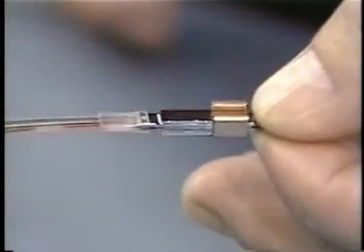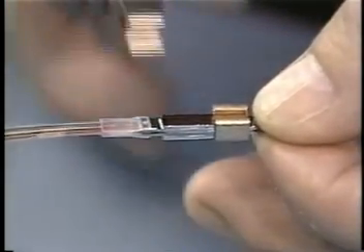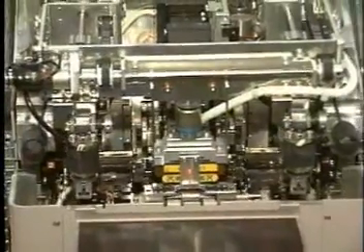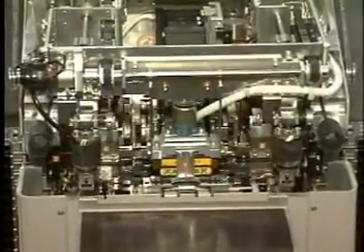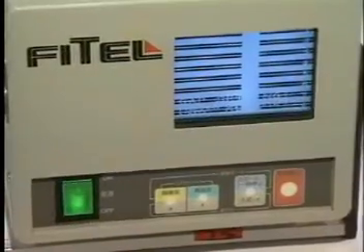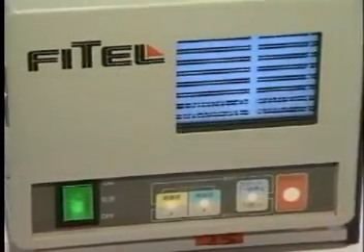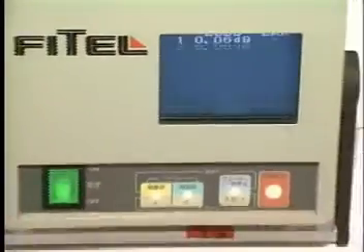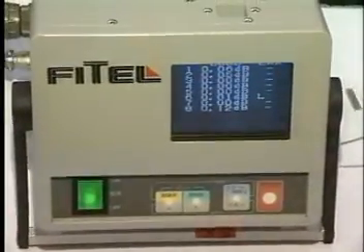Ribbon fiber consists of a number of parallel fibers sandwiched between adhesive tapes. Although a great time saver for high-volume production, mass splicing sacrifices individual control over fibers, requiring very tight fiber tolerances to get acceptable results. But why use fiber?